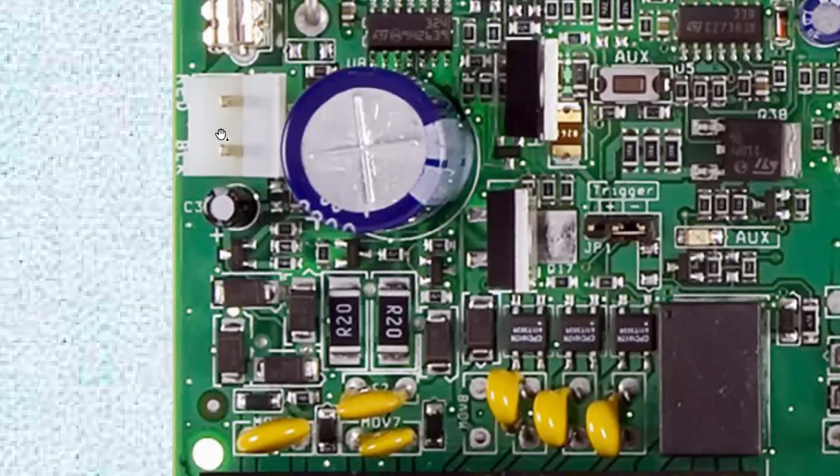I don't know. You can never tell, depending on how many active devices you have, how many motion sensors you have, how many keypads you have, how many other peripherals you have that need to be powered. And then if more current is being drawn, then it's going to stay less time. But pretty much on the average, you get about an hour of power outage, and the alarm system is still going to be powered on its own through its own backup battery.